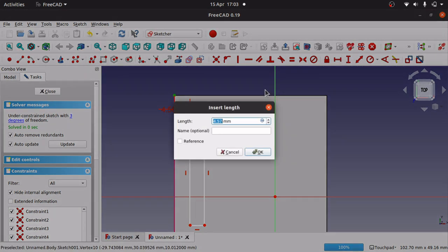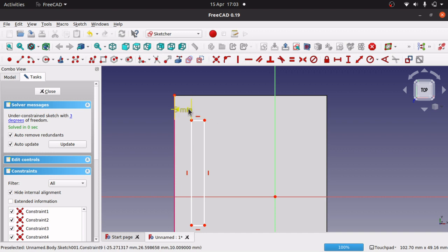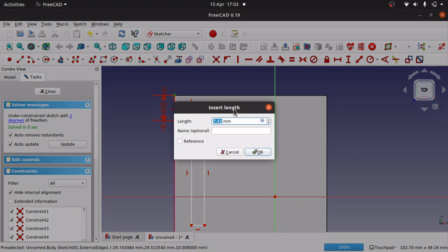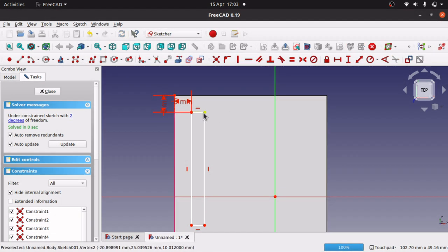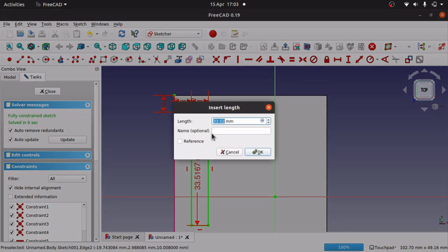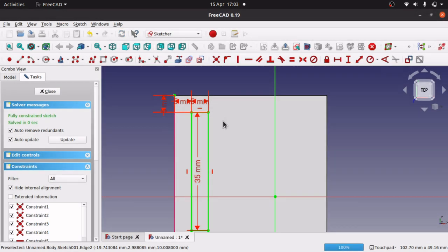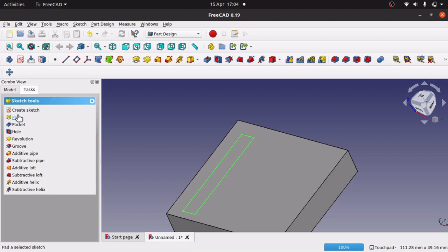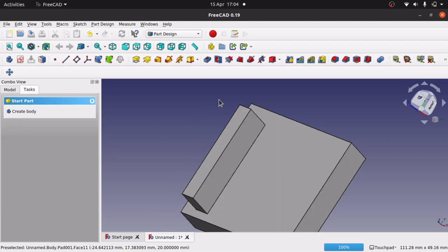and I want that sitting around about 5mm away and 5mm also away from the edge, and we want to make that a distance of 5mm. I'm just going to set the height as well, so 33, say 35. So that's sitting there, that's the feature that I want to actually mirror at some point. So close that and pad it up, so okay that.